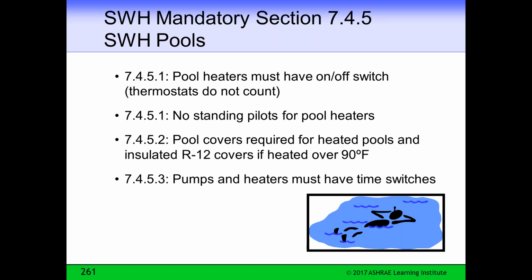Pool heaters must have on-off switches, not just thermostats. Again, this allows a user to turn it off if they know they're not going to be using it for some period of time. No standing pilots on pool heaters. This is just because we don't think the pool heaters strike at a far enough spaced out interval that the standing pilot would be a waste of energy.